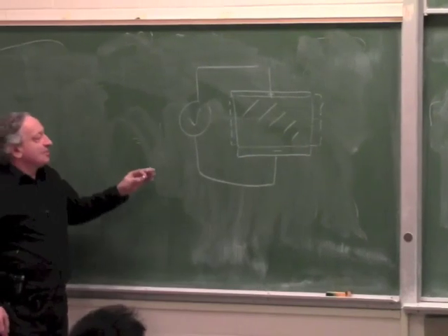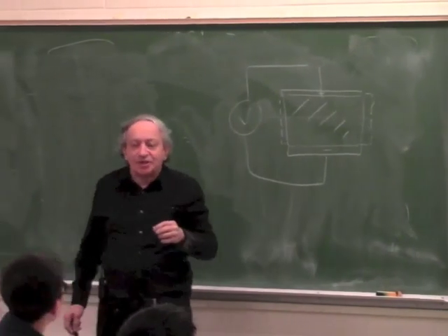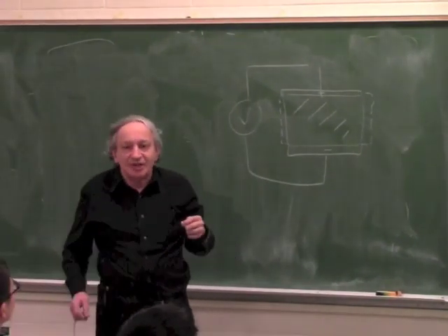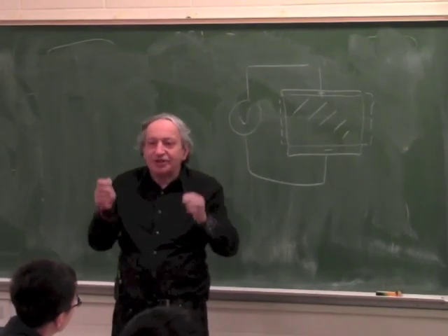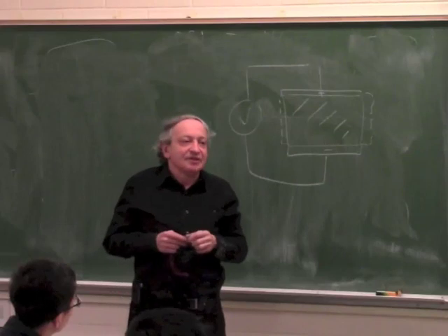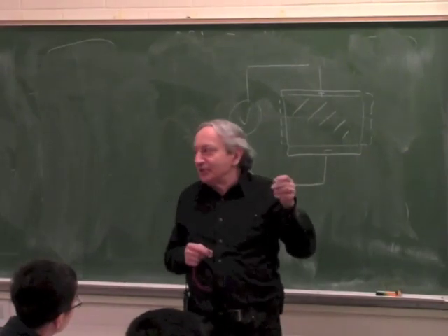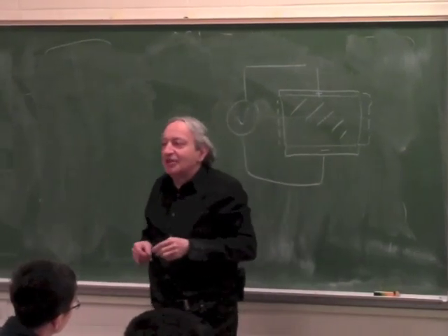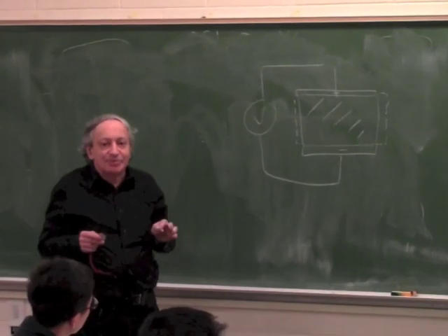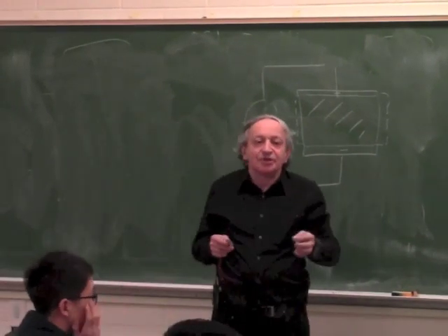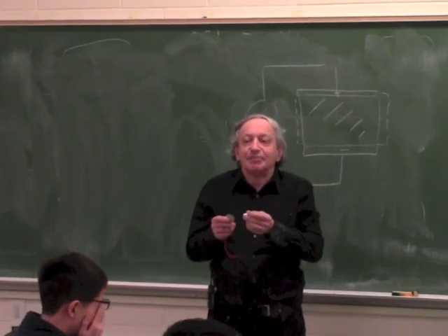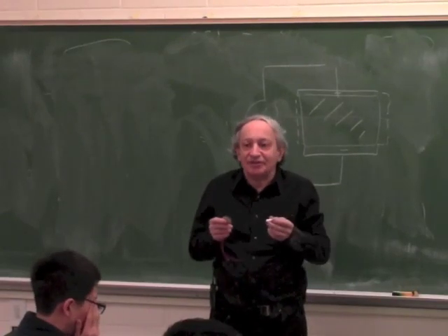Now this is a bit similar to magnetostriction. I mentioned before that if you take a magnetic material, put a coil on it, it will shrink when you apply a magnetic field. That's the reason power transformers make noise. I mentioned it many times. But magnetostriction is very simple. Whenever you put a magnetic field, it doesn't matter which direction, it always shrinks in the direction of the magnetic field.